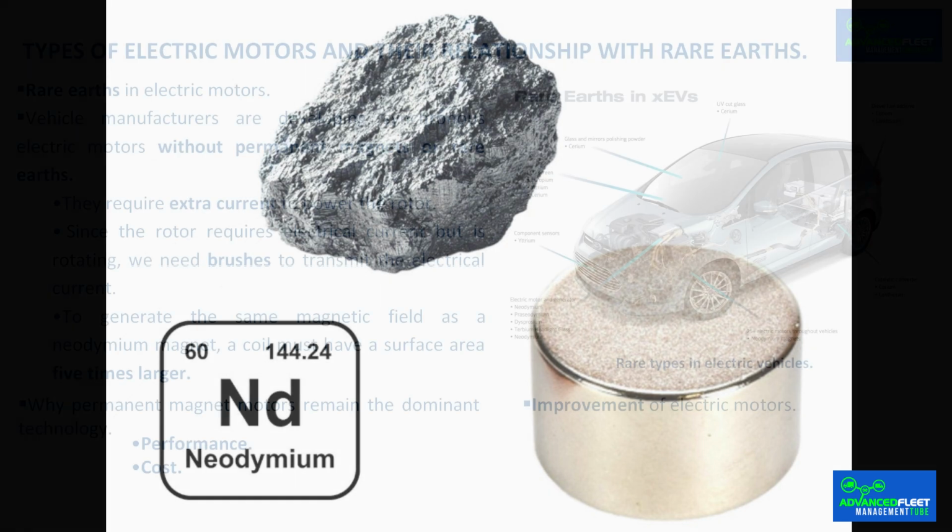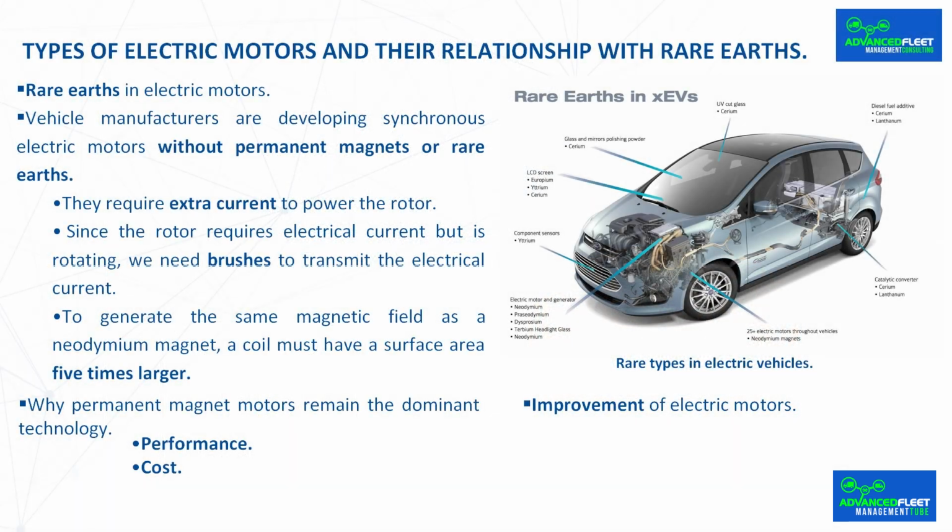The induction motor is not affected by temperature changes unless the melting temperature of the copper wire varnish is exceeded, otherwise no problems are expected. If acceleration occurs, there is no cause for concern. The problem would arise if this occurred constantly. Electric motors in automobiles commonly have cooling systems, however, the heat generated inside can be difficult to extract due to the impossibility of the rotor coming into contact with the cooling circuit.